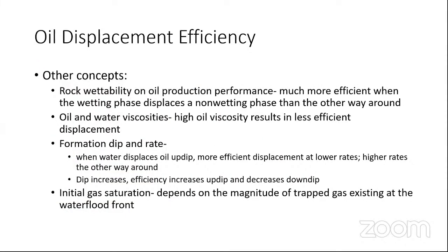So there are other concepts of oil displacement efficiency. Rock wettability: oil production performance is much more efficient when the wetting phase displaces a non-wetting phase than the other way around. You have oil and water viscosities, where higher oil viscosity results in less efficient displacement. And then you have formation dip and rate, where the water displaces oil up dip, more efficient displacement at lower rates, and at higher rates the other way around.